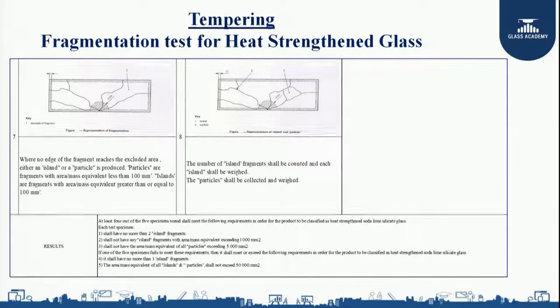So once the glass got broken, we need to see what are the number of islands and particles. The number of island fragments shall be counted, and each island shall be weighed. The particles shall be collected and weighed.